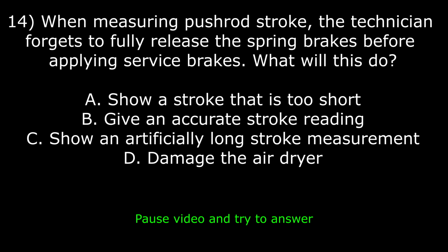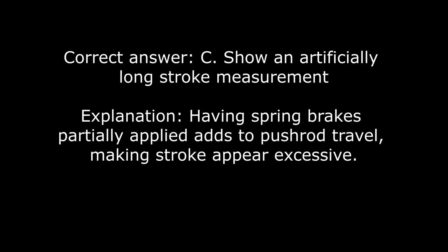Question 14. When measuring pushrod stroke, the technician forgets to fully release the spring brakes before applying service brakes. What will this do? A. Show a stroke that is too short. B. Give an accurate stroke reading. C. Show an artificially long stroke measurement. D. Damage the air dryer. Correct answer: C. Show an artificially long stroke measurement. Explanation: having spring brakes partially applied adds to pushrod travel, making stroke appear excessive.